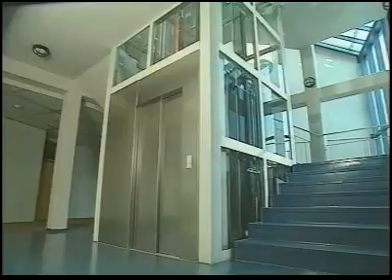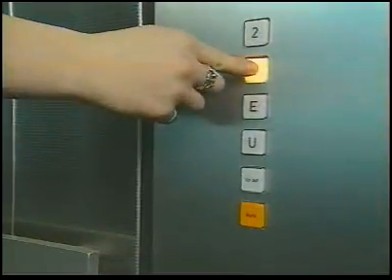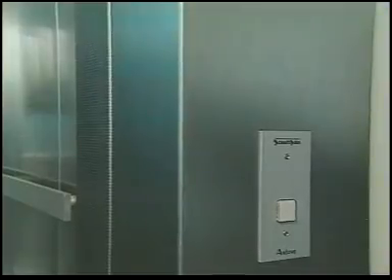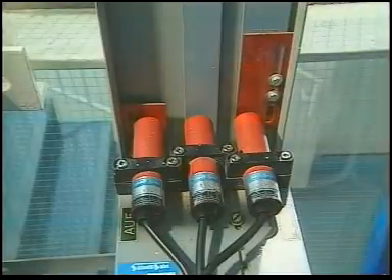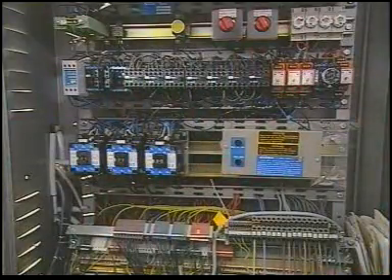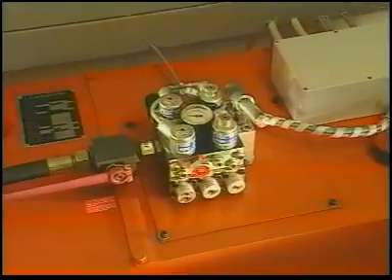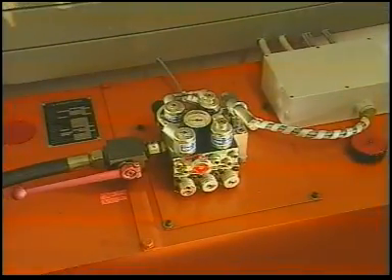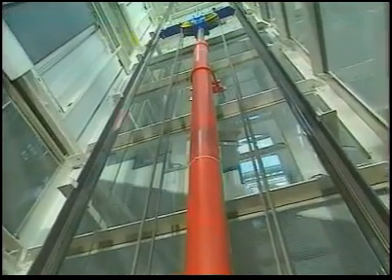Also in the elevator, these two areas are clearly differentiated. The controls in the elevator and on the door, and the sensors in the shaft which report the position of the elevator, together with the controller, form the electrical control part. The solenoid valve is the interface to the power part, consisting of the power pack, the valve in its function as a final control element, and the hydraulic cylinder.